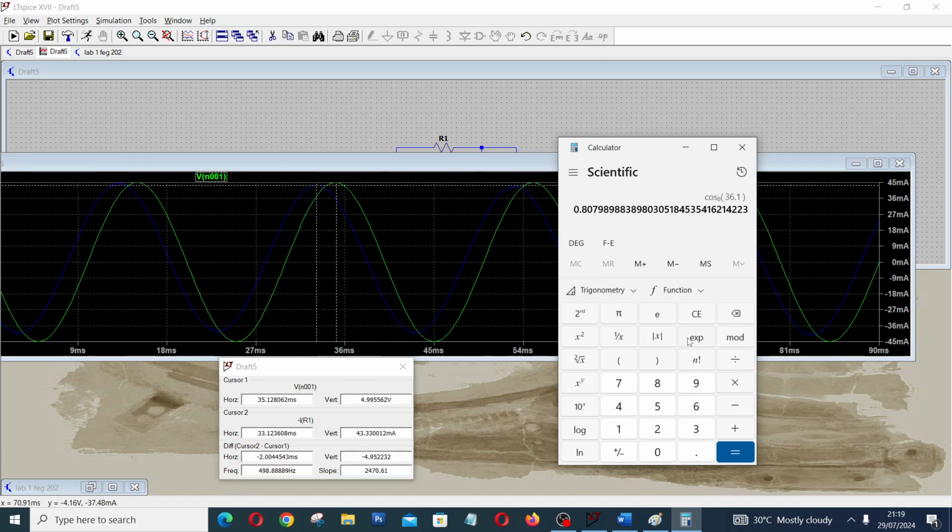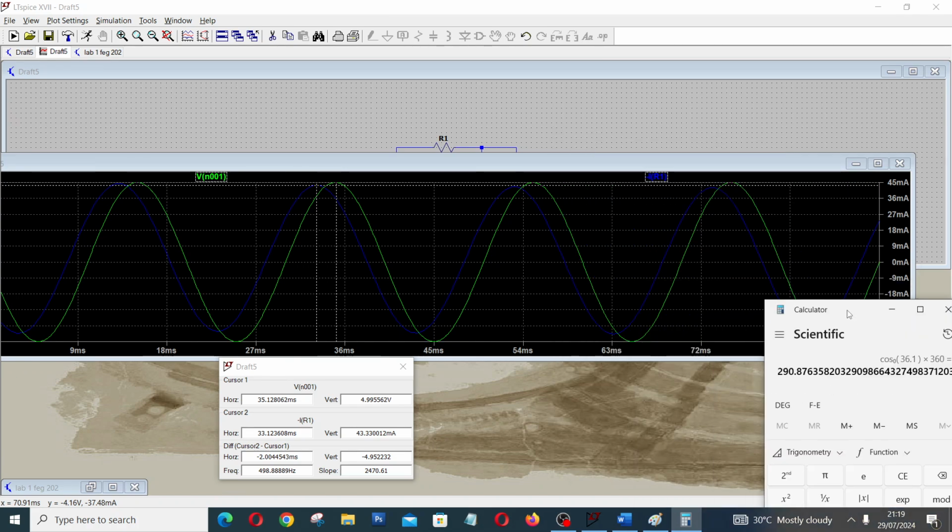So the introduction of the static capacitor has helped us to correct the power factor from a very poor system to a very good system. If you remember what we discussed in the theory, or what textbooks normally teach, power factor should be a value between 0 and 1, but 1 is the ideal value. Anything close to 0 should be avoided. It's a very poor system. So from this simple explanation, you see that the power factor has been corrected using static capacitor.